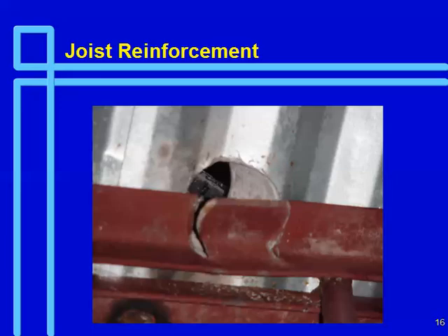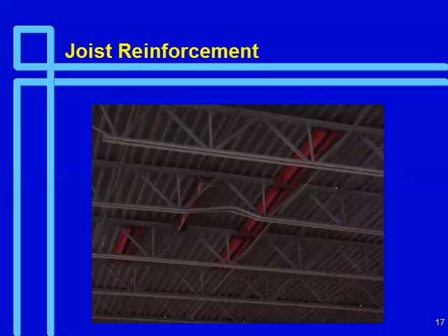This is not a good picture. Can you see it okay? This joist in the tension chord has a big old hump in it. That's more than likely our erector friend. He probably dropped the joist. And then, screw it, I'll put it back up, and maybe they won't even notice it. And the fact that it's a tension chord, it's not so bad. But it would need to be fixed, certainly.